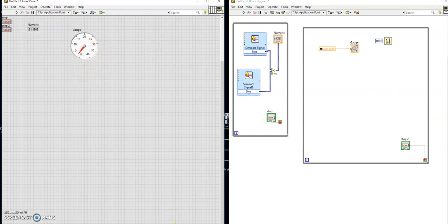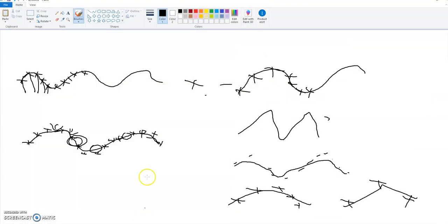So let's change our frequency. Our sample frequency is way too low. It's 1 Hertz at the moment. So what is our highest frequency? Our highest frequency is the noise one at the moment. We just clean this up.